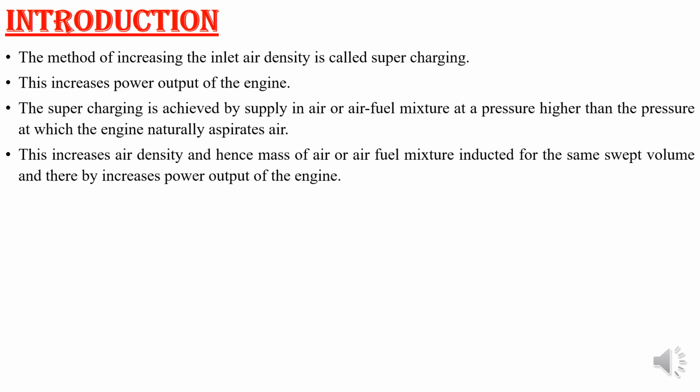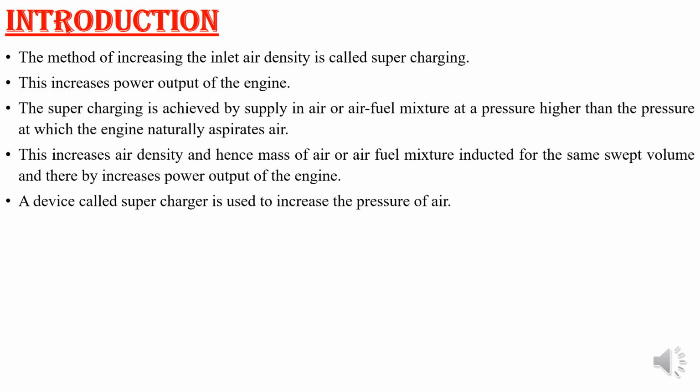Whatever device we use to increase this air density by increasing its pressure, that device is known as a supercharger. Remember, a supercharger is used to increase the pressure of air, thereby increasing the density of air and the power output of the engine. So this is the main concept behind supercharging.